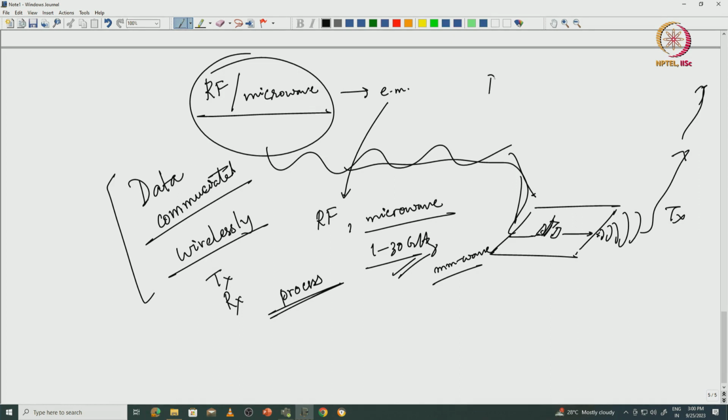So the RF device engineer is in a very tight spot, because he or she has to cater to an increasing demand on things like PA efficiency, gain, power, linearity, and also size of the die. You need miniaturized, lightweight, thermally managed dies, but they should give you outstanding efficiency, gain, power, linearity.